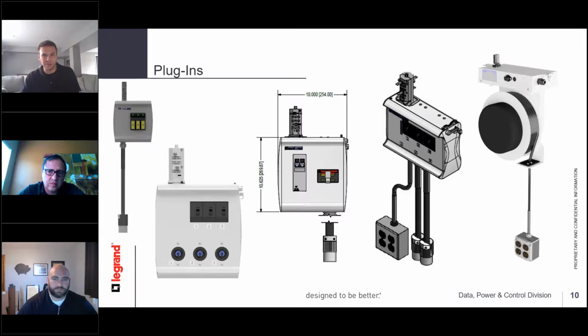Anything the customer wants, we're going to make it, right? As long as we can abide by UL 857 and NEC codes, we can do that. And by custom, we mean that it's not going to be a long lead time or anything like that. That's just our business. In industrial facilities, guys will tell me, hey, I need a 520 quad, an L630, and an L1530, all in the same plug-in unit. Can you do that? Well, sure. That may not be one we've done before, but that's not a problem.